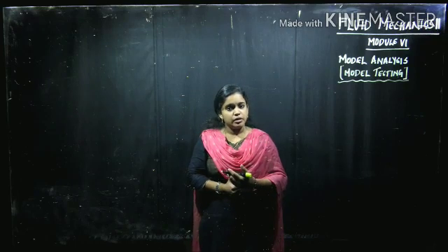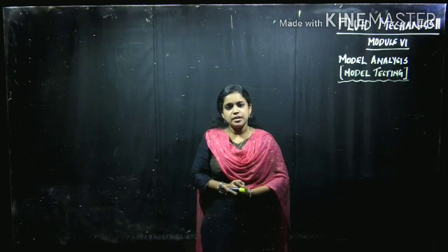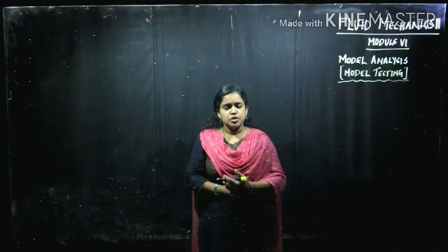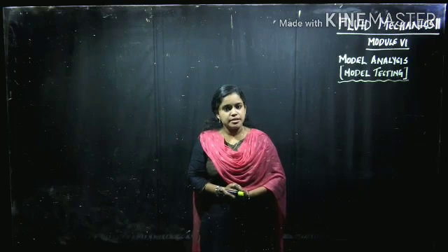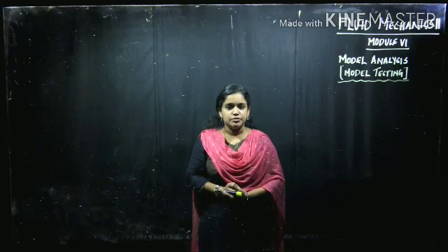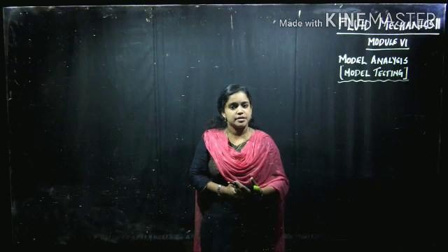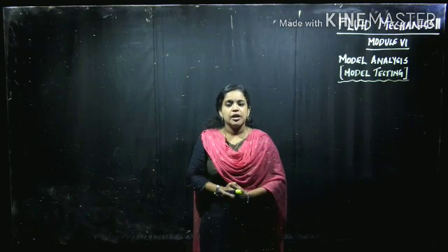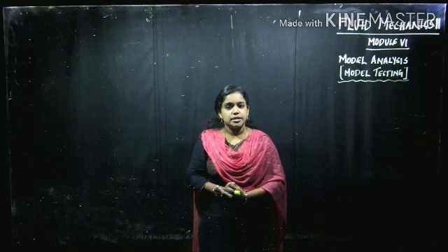What is the reason why we conduct experiments on models? The reason is that the experimental results are more validatable than theoretical values. For example, if you are taking the construction of a dam, we know that a dam is a massive, costly structure. After construction of the dam, any changes to the structure are difficult. So before construction, we should make sure that our design is exact and maximum performance is obtained from the constructed hydraulic structure. To make sure that our design is correct, we will be constructing a small model of the actual structure, and all the experiments will be conducted on this model.